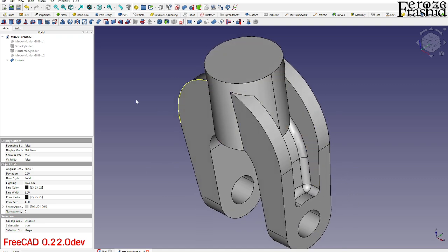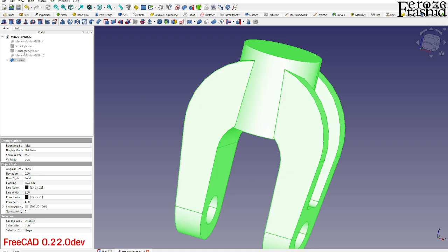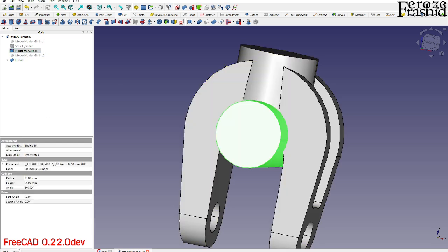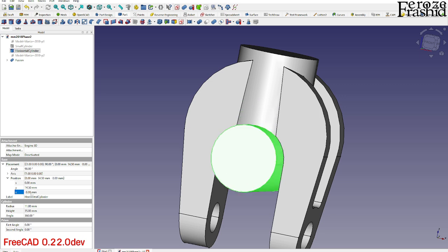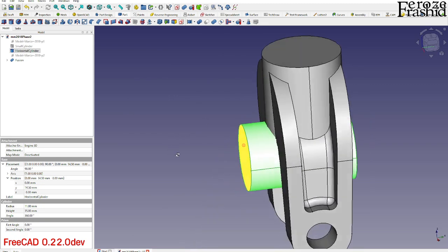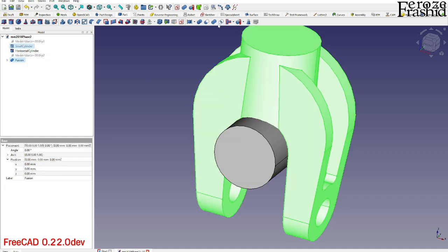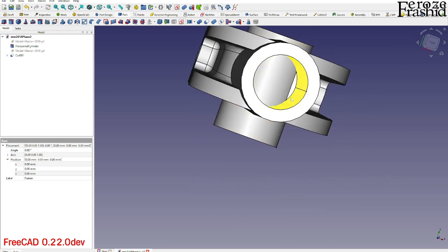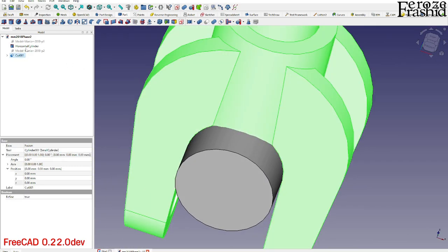And then take, oh, we'll have to relocate the horizontal cylinder. So it was 8 millimeter down. Remember that the difference between two centers was 8 millimeters. So in Z, say -8. That moves it downward, and that should work. Okay, so what I want to do is take the small cylinder out of the fusion, and then finally, let's see. Maybe we'll have to do something about it. Okay, let's make this deduction, see if it works.